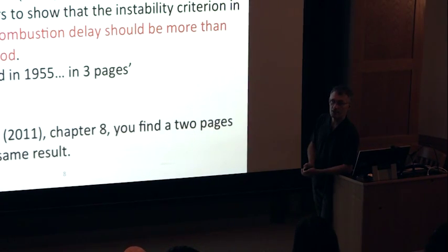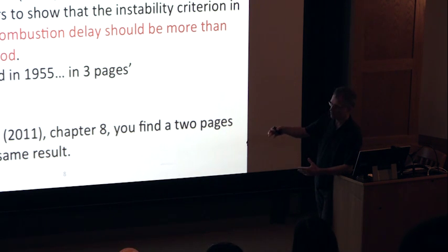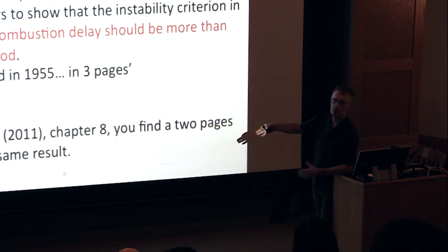And I really see a big problem at the moment. I see people running codes everywhere. You've seen nice pictures, nice movies, all that. But please don't do that only. If you just run the code, you're lost, okay? You need to get the theory running. The code is telling you something about the flame speed. You need to check if that makes sense. It's telling you something about the adiabatic flame temperature, go look at theory. Don't just run codes. So that would be my conclusion.